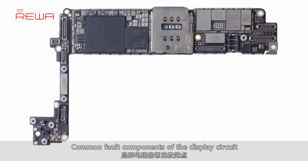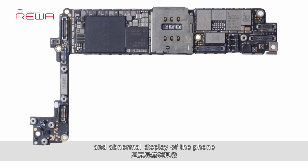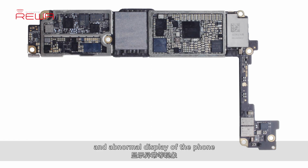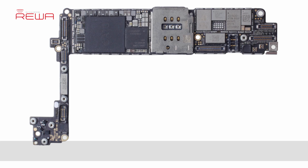Common fault components of the display circuit. Damage of J4502 can result in no display, no backlight, and abnormal display of the phone. Damage of U3703 can result in no display, stuck on Apple logo, and abnormal display of the phone. Damage of L3901, L3903, or L3902 can result in no display of the phone.